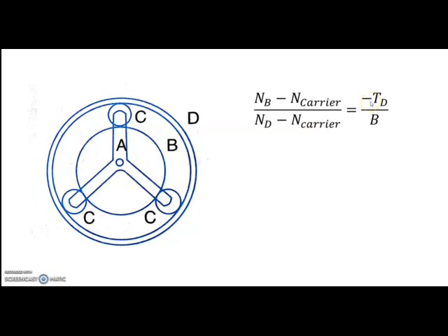Why the minus sign? Once again, let me clarify. If B rotates clockwise, C rotates anti-clockwise, and D rotates anti-clockwise because C and D are annular gear. You know, in annular gearing, the direction of the gears is the same. So if B rotates clockwise, C rotates anti-clockwise, and D rotates anti-clockwise. So finally, B and D direction is opposite. That's why the minus sign is there.